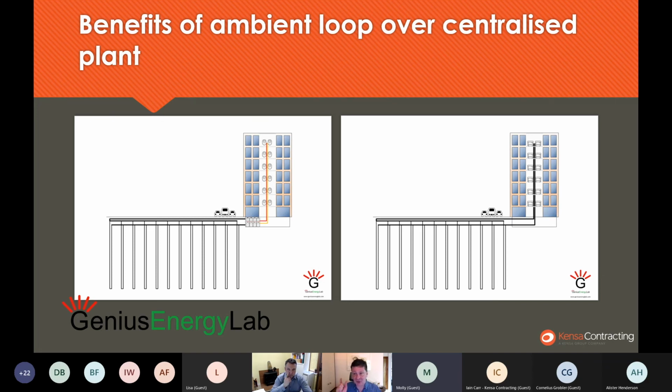What I would say is, if you look at it in the cold light of day, stony-heartedly, as a technical solution, every single time this comes out better. Every single time the distributed heat pump model comes out better. And that's to do with several things. First of all, we're running this district heat network at the lowest common denominator in terms of temperature, i.e. the highest temperature that we need in that network, which almost always means 65 degrees to deliver 60 degrees hot water, domestic hot water into the dwellings. So you're almost always fixed on that 65-degree temperature.